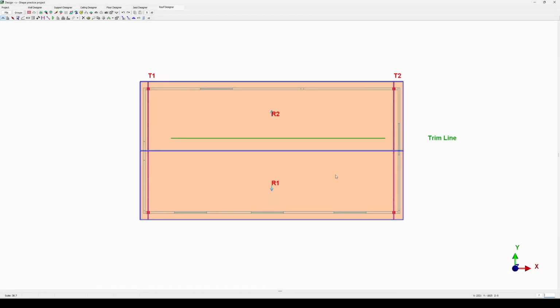After inserting your first two trusses, we need to make sure that the trusses conform to your general design practice. What we'll do is go to the selection tool, select the truss, and move it closer to the inside of that wall. In this case, I'm going to be moving my truss 100 millimeters away from the inside of the wall to the center of my truss.